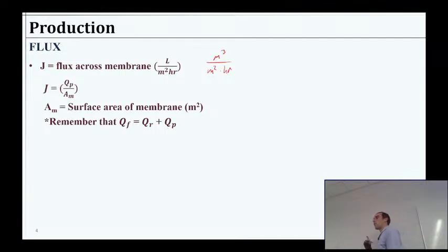And keep in mind that when we are talking about flux, we are producing water. This is flux that crosses that membrane. So that's based on the flow rate of the permeate, not of the flow that we're giving to the membrane. The giving to the membrane, that's the feed, right? We're shoving a certain amount of water to the membrane. Some amount of that crosses, that's the flux that it has to cross. So we're going to use QP. Crosses the membrane.